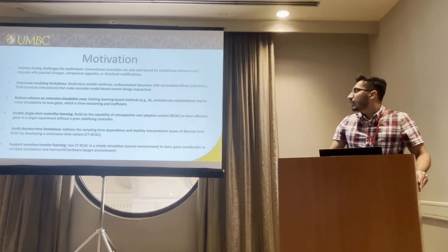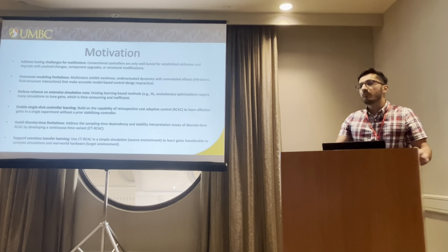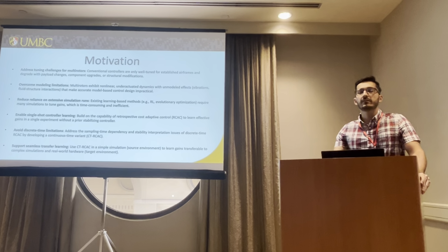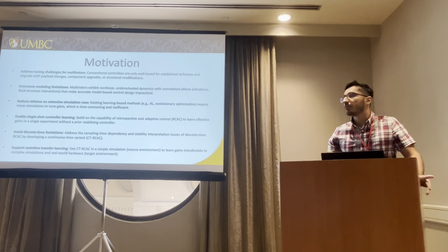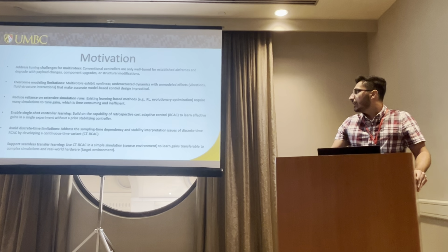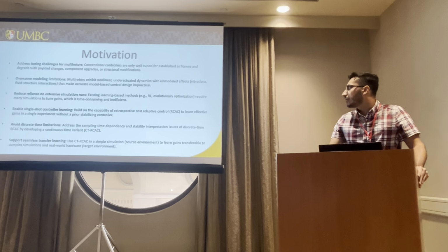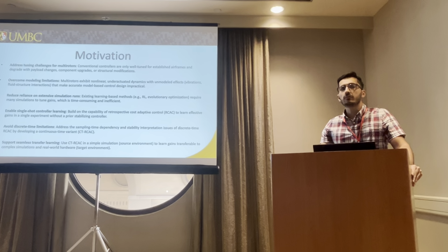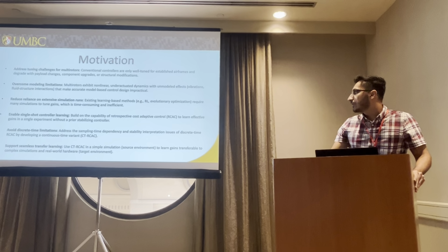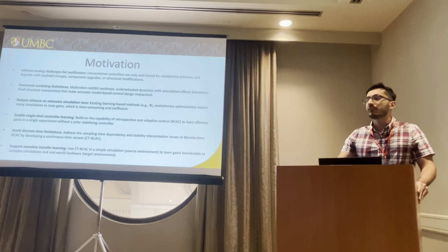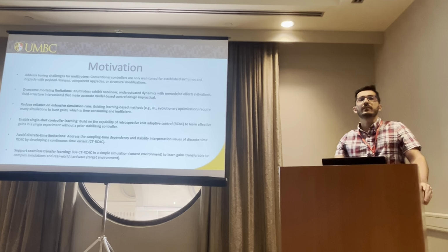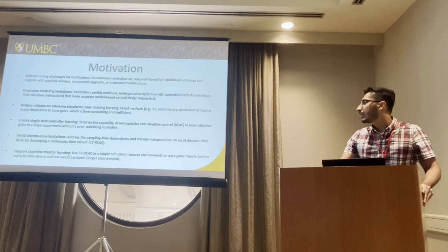So there is a motivation for learning a proper policy in only one iteration, in a single shot, without going through many iterations and without the need for a prior stabilizing controller, just learning from almost nothing based on input-output data. In this work, we want to show the application of continuous-time retrospective cost adaptive control to multirotor flight control. Because we are using a continuous-time controller, we don't need to deal with the discrepancy that arises when implementing a discrete-time controller for a continuous-time plant.